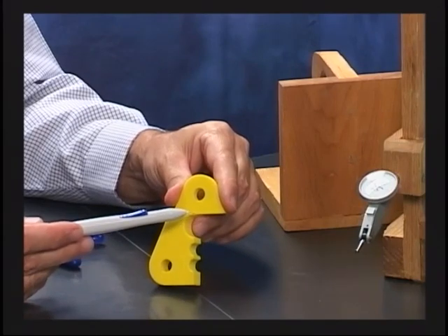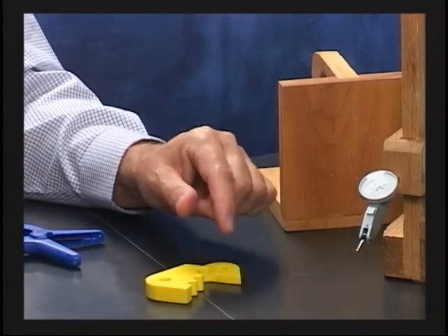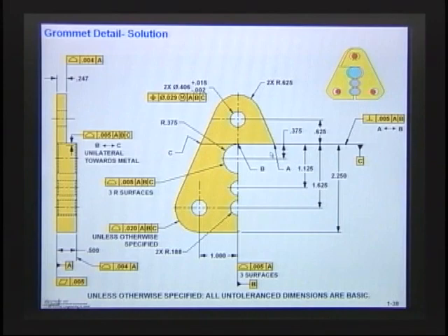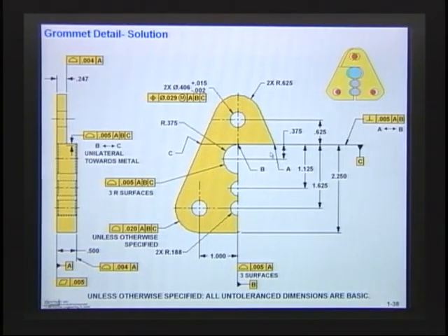Now, just be aware here. Let me show you on our graphic. Let's just go back to the graphic for a minute. And on the graphic, I'd like to show you just some things. If they come in with a coordinate measuring machine and they were to just touch 2 points, by just touching 2 points, you wouldn't know much about that surface. So they would probably have to touch a number of points on that surface. And when they did, they would find out whether it fell inside of a tolerance zone, right?